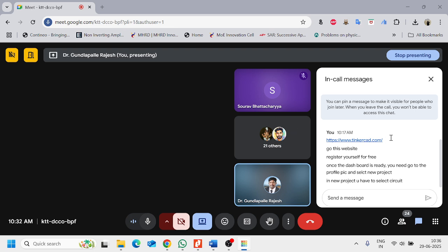And for 1000. So now, since we have one LED, we will set up two LEDs now, right? We'll take one more LED and write the program. I will repeat the same thing, and LED 1, first time it has to be low. So when the green LED is high, the other LED will be low, and when the green LED is low, the other LED has to be high. So this is your program.